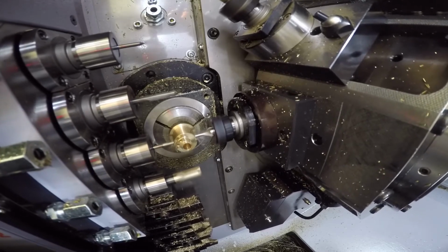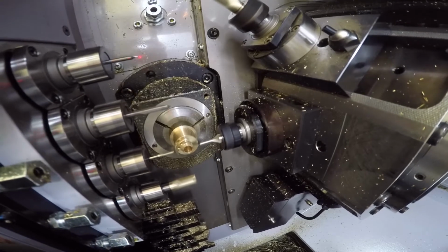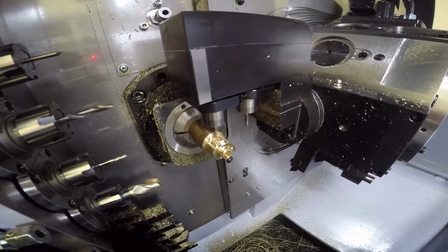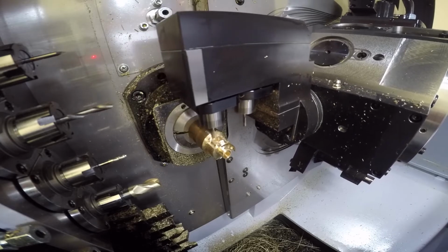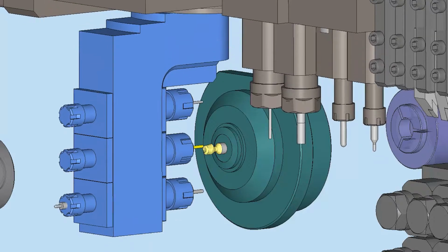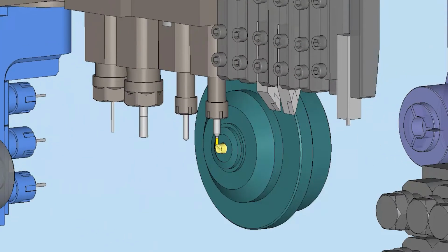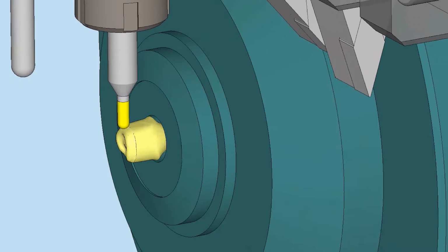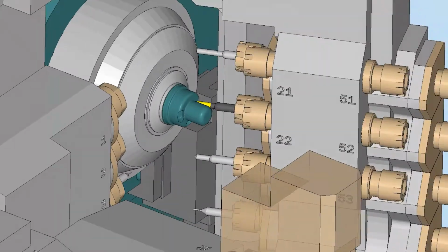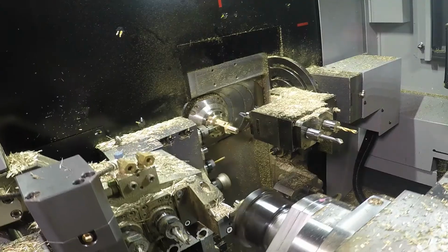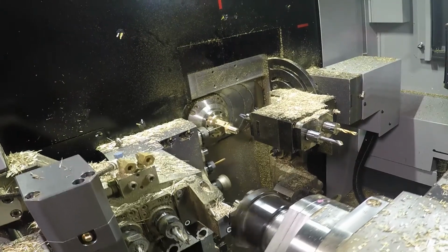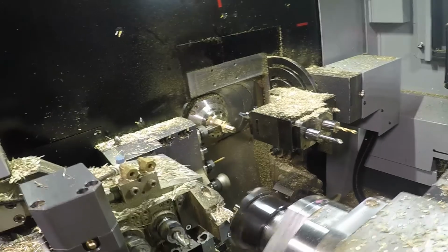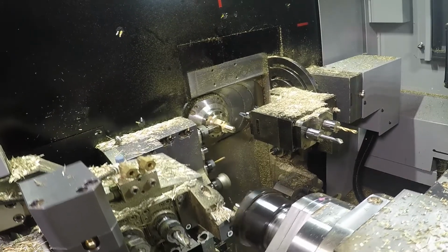Swiss-type CNC turning centers are commonly used to machine complex parts in small lots with many cutting tools in a single setup. These machines are typically 32 millimeters in diameter and less and have incredibly small footprints while using sliding headstocks, guide bushings, gang slides, and posts for tooling. But they also support secondary spindles and collinear axes. The parts run on Swiss machines are getting more complicated. And in response, the machines themselves are getting more complicated.